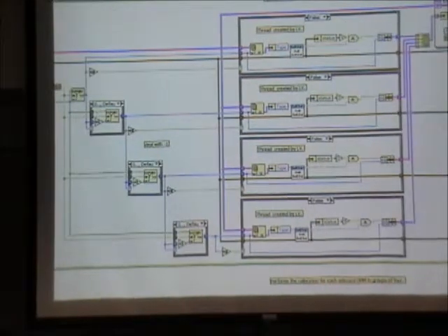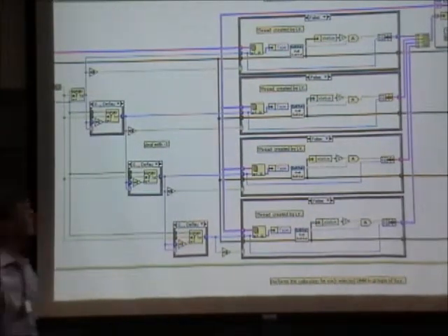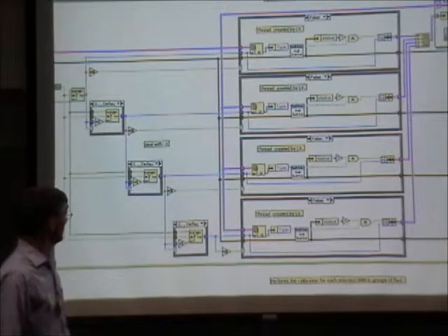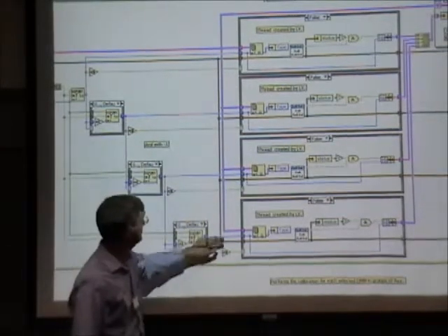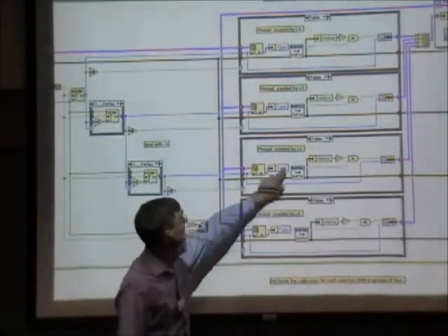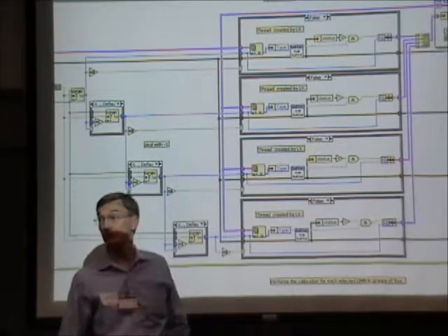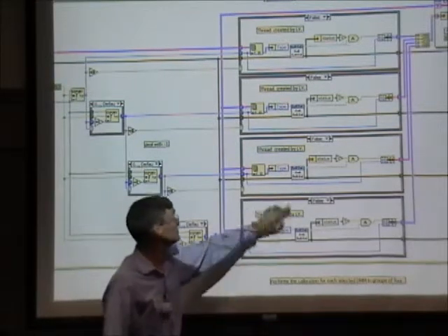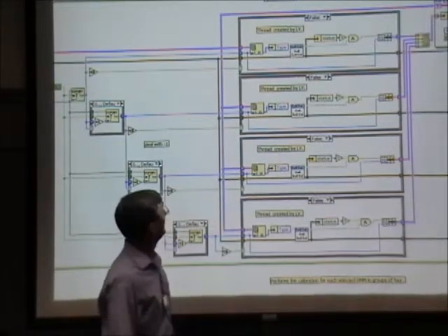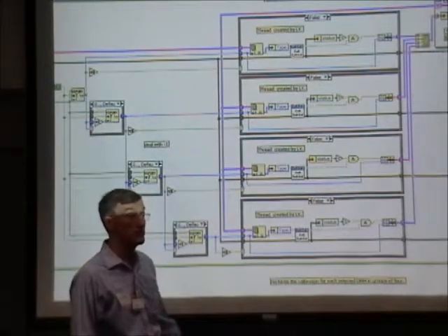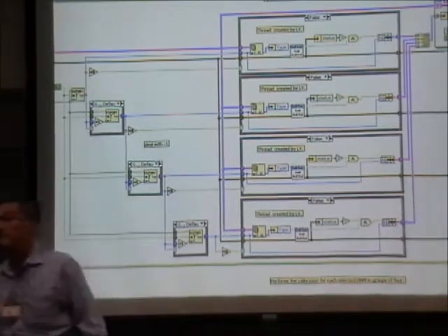Is enough of that on screen? Yeah. So we got to this point in the code review, and I'm looking at this and I'm saying, oh, cool. You've divided up your error line. You've got the same thing here that you can't read that's doing instrument calls for self-calibration. So this is the same VI. And you're trying to get some efficiency here. You're running them in parallel. No problem, LabVIEW, you can do that.